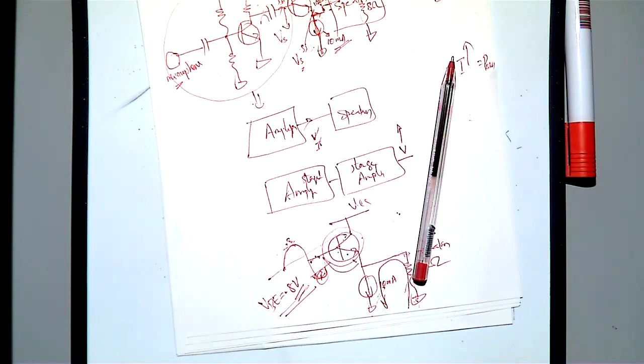So here we have connected plus 5, here we have connected minus 5, and this current source we biased for just 32.5 milliamps, just an example, and your speaker has 8 ohm impedance. Then what is the current I1? This I1 equals IC, because our assumption is IC is approximately equal to IE, plus Vout by RL, because that is the current flowing here, this I1.